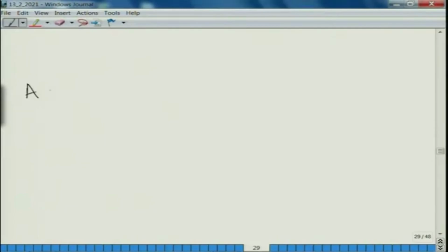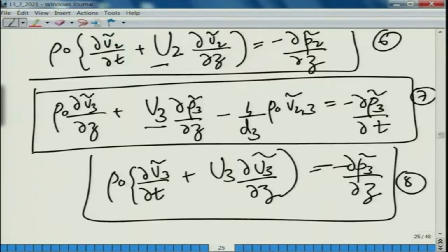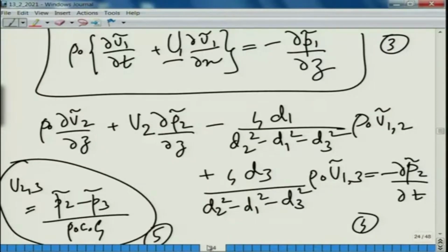So, the A matrix is then given by this, and here note one more thing that I forgot to tell, and that is that we have incorporated the convective effects of mean flow through the underlined terms. So, here we have these underlined terms, u2, u3 and so on, and u1 also in this duct. But for simplicity we can ignore the convective effects of mean flow altogether in the ducted system, and we can just consider the dissipative effects of mean flow. And how do we do that? We incorporate the dissipative effects into the perforate impedance expression.